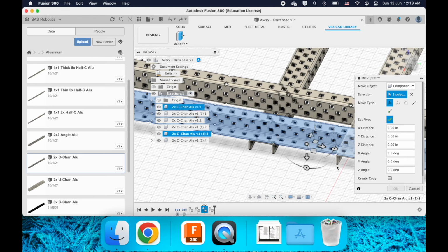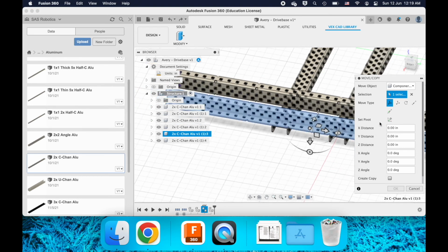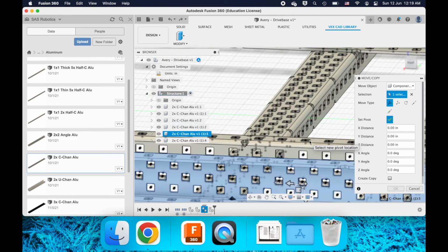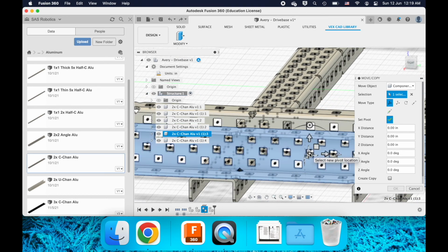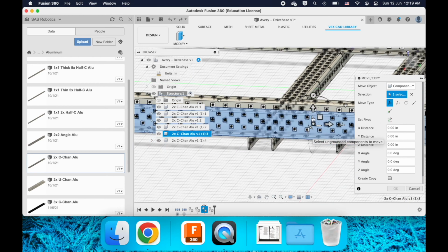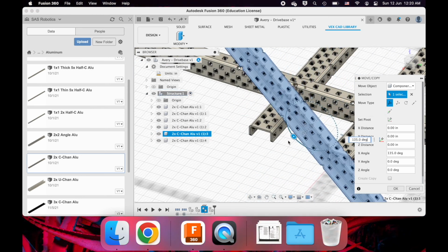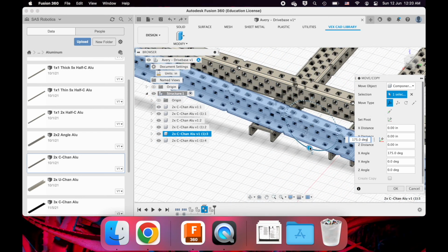So I'm going to set a pivot in the center of this piece, at this dot in the middle on this side, and click the check mark. Once you click the check mark, your pivot is set there, you stop adjusting the pivot, and you actually move the piece relative to this new pivot.